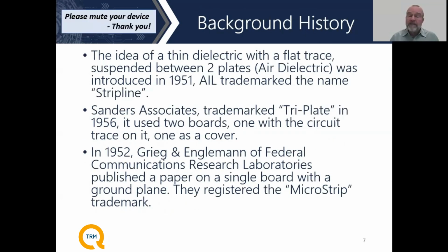A little more detail as far as some of the strip line and microstrip pieces here. If you take a look at the idea of taking a coaxial line and making it into a flat plate separated by two metal plates, it was introduced by AIL in 1951, and they trademarked the name strip line. Now, the thing that's interesting about the AIL patent or trademark is that it used an air dielectric. So it was really a suspended strip line, not a true strip line as we think about it today.